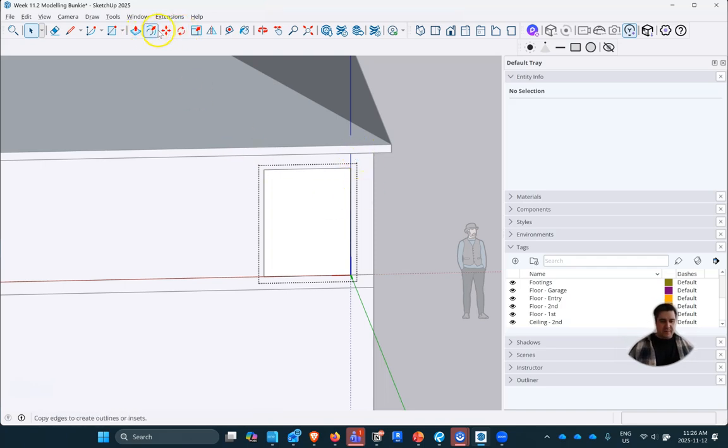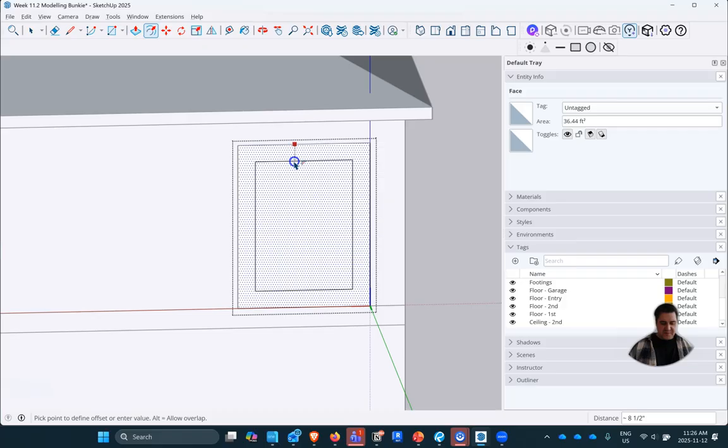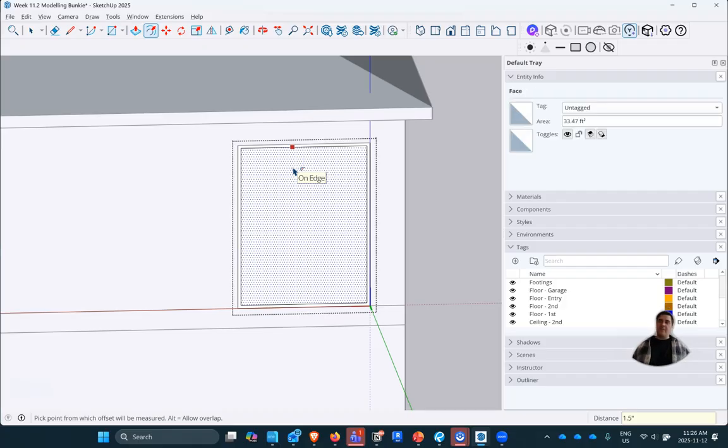So we're going to offset in 1.5 inches. And even with a door, you would typically have that on the bottom and on the top, because you would have some sort of track on the bottom. Often what will happen in construction, the track is pretty thin, but you put the track on the subfloor, so that when you put your flooring inside, it hides and buries 3/4 of an inch in that track, so the track only might stick up a tiny bit, but your flooring is really what's covering it.